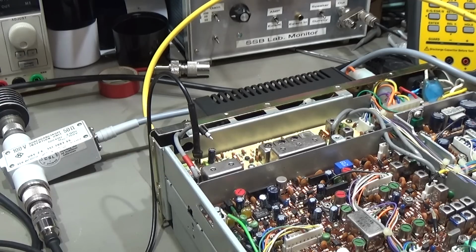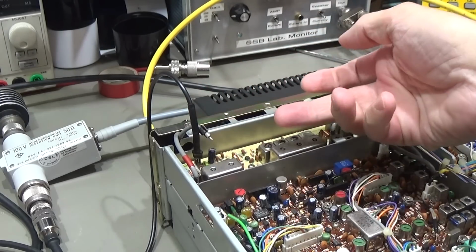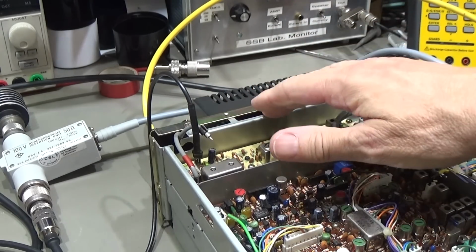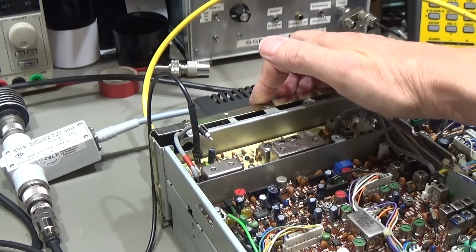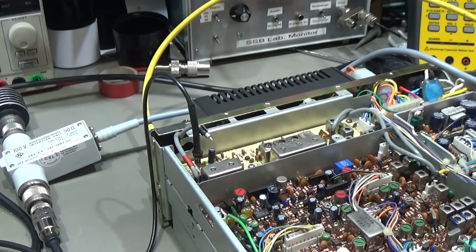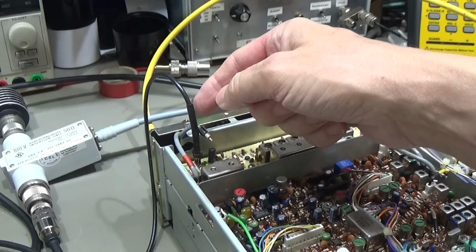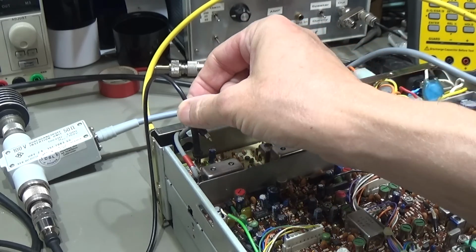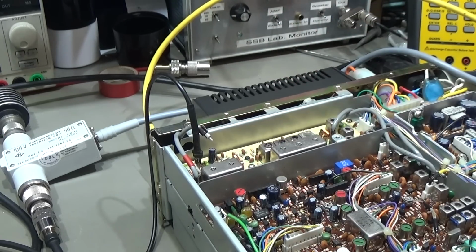Okay, so the next test we can do is we pick here our signal coming out of our RF board, and we'll supply then our hybrid power amplifier, right? So that is connected, and according to our service manual we should see here minimum 230 milliwatt or more than 3 volt into 50 ohm, of course. So let's see what that means.